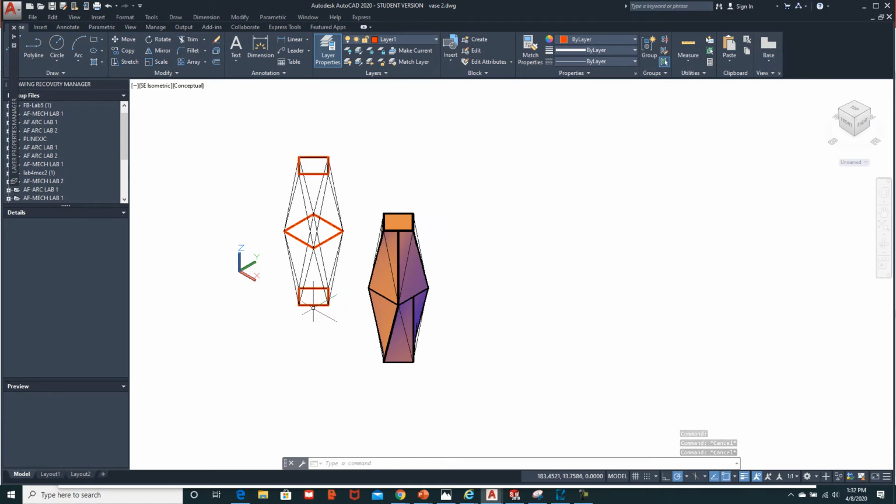We create 3 different shapes, and each of those shapes is at a different z height level. And so typically what I'll do is I'll create them all on the ground floor or at the XY elevation of 0, draw all 3 of the shapes, and then I'll move them with either 3D move or just a regular move command in the Z axis to 3 different heights. And so if this is 300 millimeters, we can change the Z value from this one to 150 and then this one to 300, and we can keep the Z value of 0 for that, and that will stack these 3 items up.